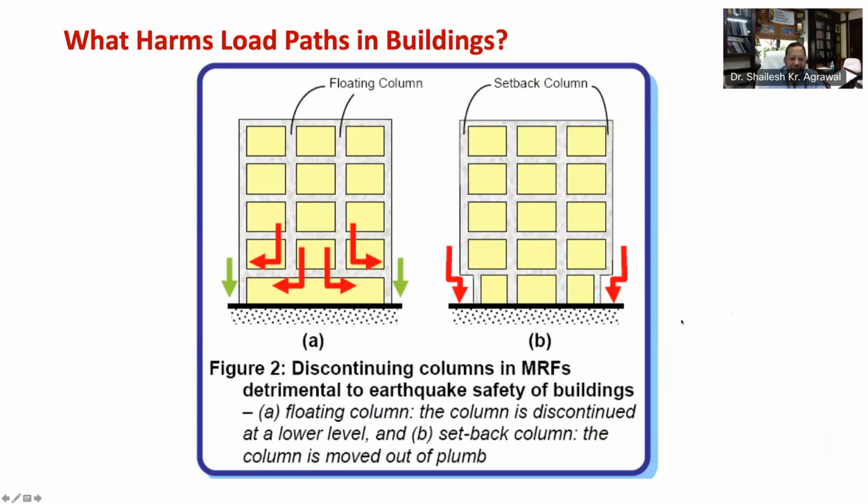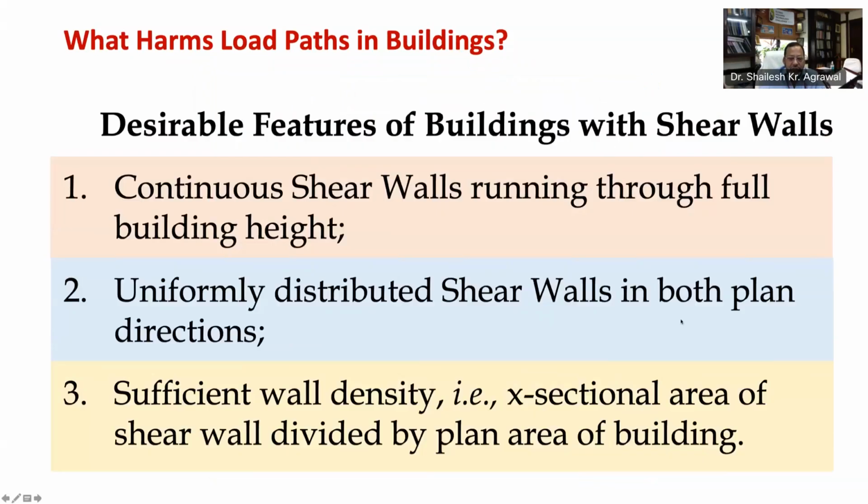Now let's understand buildings with structural walls. Structural walls are also called shear walls as they have large stiffness and strength in the length direction and provide very good load path. As told you in an earlier tip, the buildings with shear walls perform well during past earthquakes.